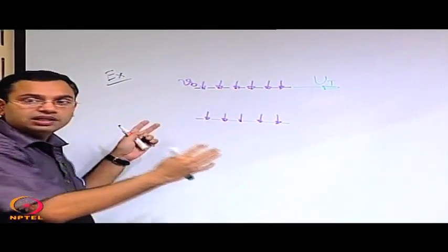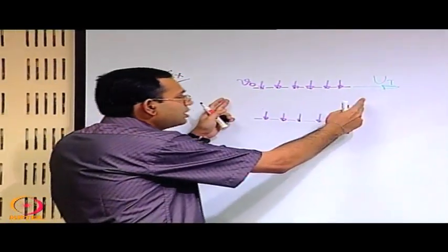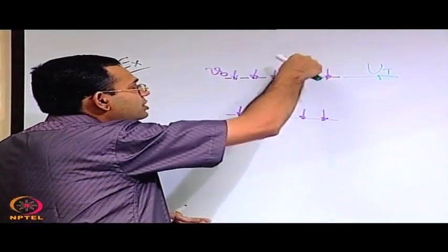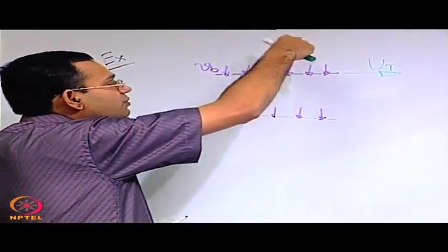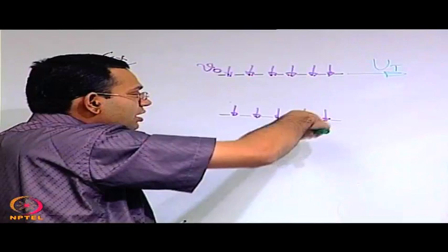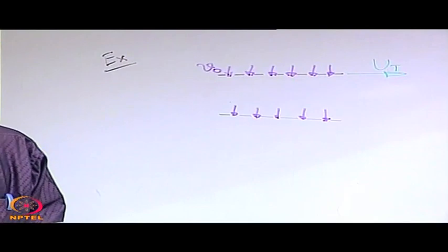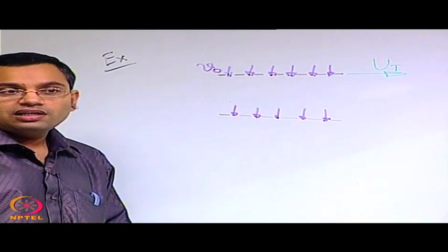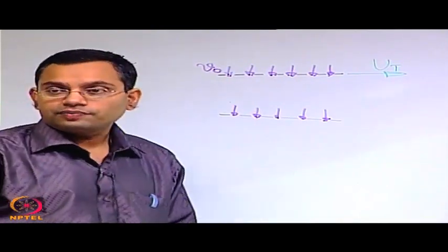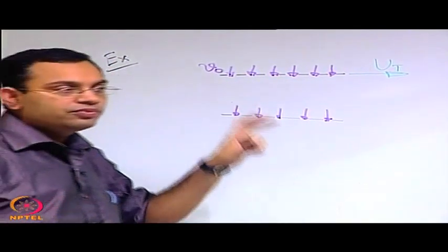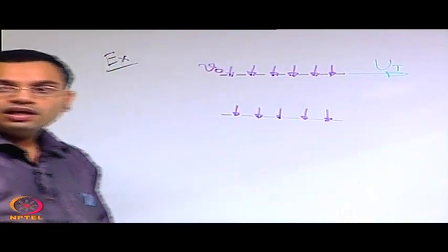Assume that there is zero pressure gradient, that means the pressures at the inlet and the outlet are the same. The only extra thing beyond what we considered in that problem is that now you have a transverse motion because of some suction effect, which is sucking some fluid from the top and releasing it through the bottom. So there is a forced vertical component of velocity. We will later see that this type of suction is not irrelevant; it has some consequence with the boundary layer theory, and we will come into that later, but right now we are just treating it as a simple problem which may be treated mathematically in an elegant way.